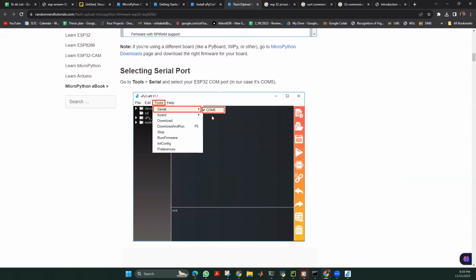Once you connect the ESP32 to the IDE, you will be able to see the relevant port which is connected to the ESP32. You need to have that port mentioned in there. Otherwise, you cannot really do the communication properly. So we will see whether it appears on my computer as well.